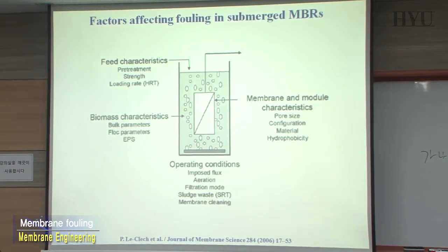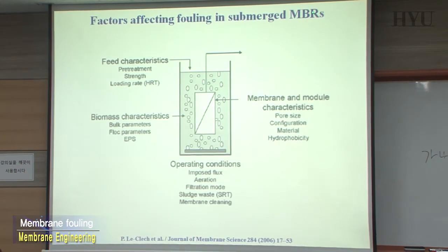By definition, when you are working in membrane bioreactors in the submerged configuration, that means you are putting your membrane in the biological tank where you are just discharging all your waste. Inside you put your ultrafiltration membranes, and that operates in a different way than normal. You make a vacuum inside so that the clean water will penetrate and you extract clean water. That's what is going on in this MBR.